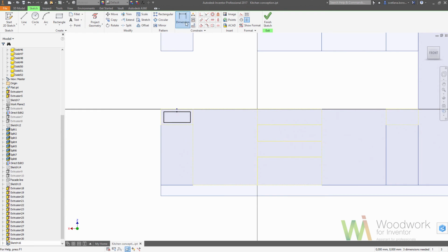Now we are defining what is the offset from the top, which would be equal to the thickness of the board, which is like 18, plus some oversize. So in total we get 28 millimeters. As you can see, we can use mathematical expressions.